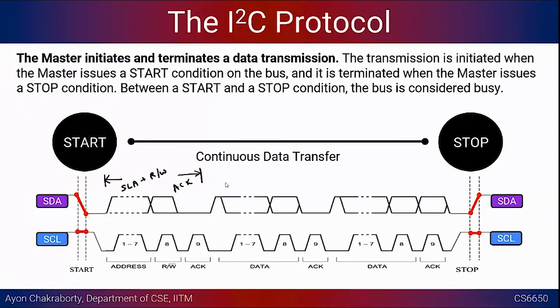You need to be more specific and maybe send some kind of a register address, right? That is how the libraries will be implemented. So after this handshaking takes place, you need to send out some more relevant information for the sensor to understand what kind of data you want to write. Let's say you want to write data.